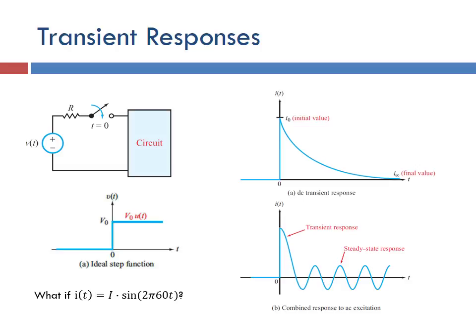The way I look at this one in A is, all the way up to 0, I have that same circuit where the switch isn't being pushed, so there's no current flowing, so everything is off. As soon as I press that button, now maybe I have a charged capacitor in there or some other circuit, and immediately that's going to jump up and give out as much current as possible, but that's going to fade off because it's not recharging. It's essentially depleting itself. So once we get out to a sufficient amount of time, we're going to have almost no current coming out. You can even think of that, if you want to go really conceptually, as like a battery dying.